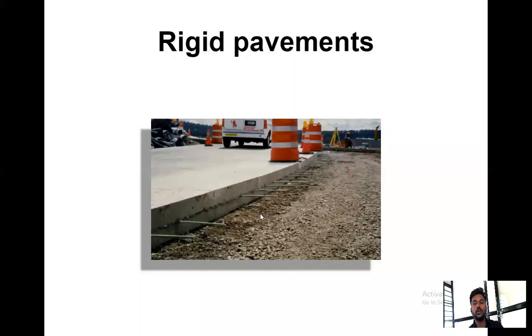Likewise, the steel rods are placed to achieve the proper bonding between two adjacent lanes or layers of the concrete. To achieve the proper bonding between two adjacent layers, provide the steel bars. Also, when there are temperature stresses and the concrete tries to elongate, that binder or the steel rods try to keep it in the proper position. So this rod acts as the binder between these two pavement layers.